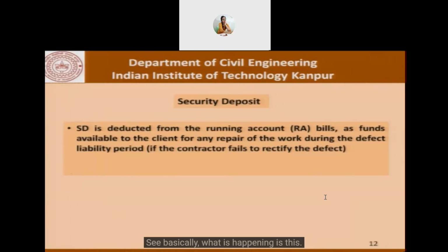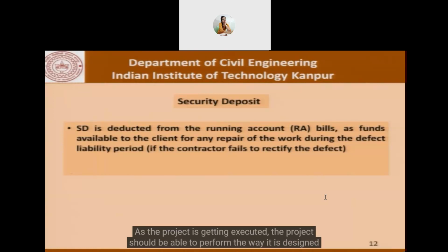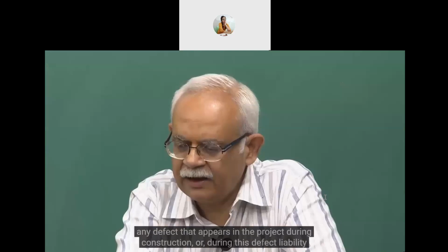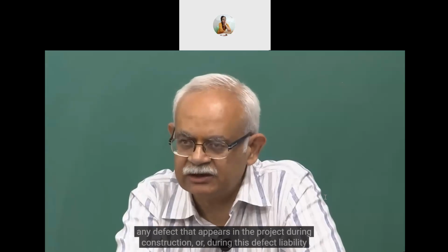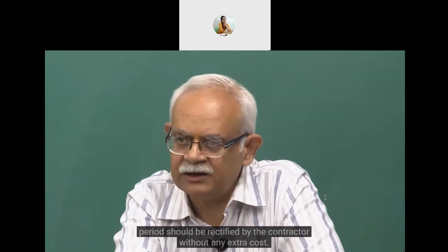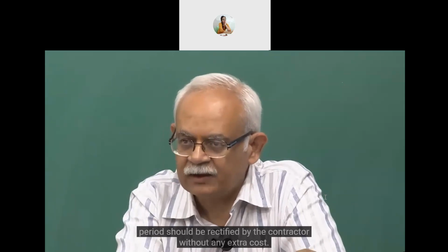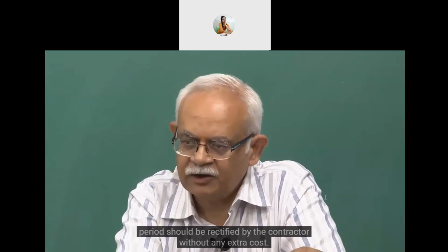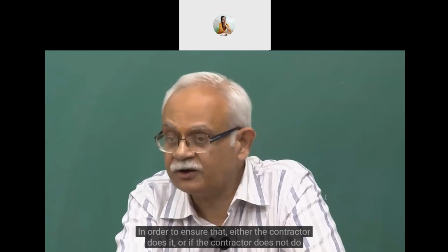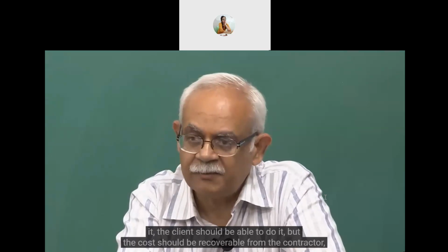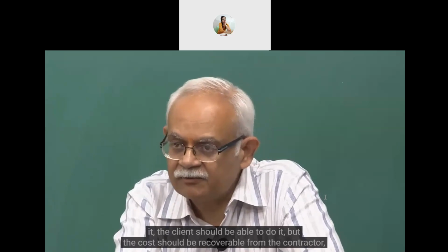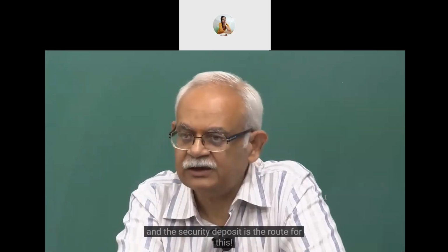See, basically what's happening is this. As the project is getting executed, the project should be able to perform the way it is designed to perform. The contractor is responsible for ensuring the quality of the project and ensuring that any defect that appears in the project during construction or during this defect liability period should be rectified by the contractor without any extra cost. In order to ensure that the contractor does it, and if the contractor does not do it, the client should be able to do it, but the cost should be recoverable from the contractor. The security deposit is the route.